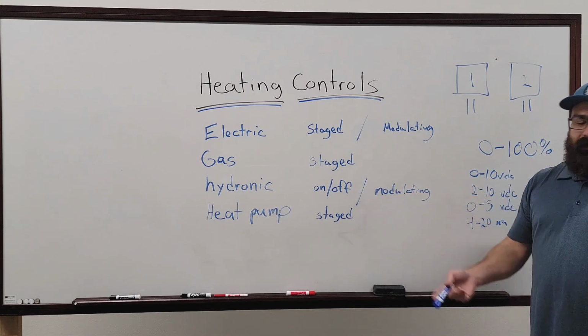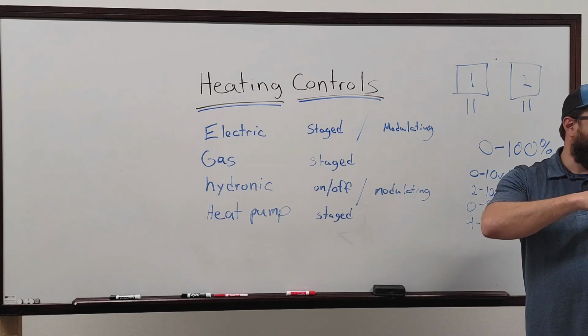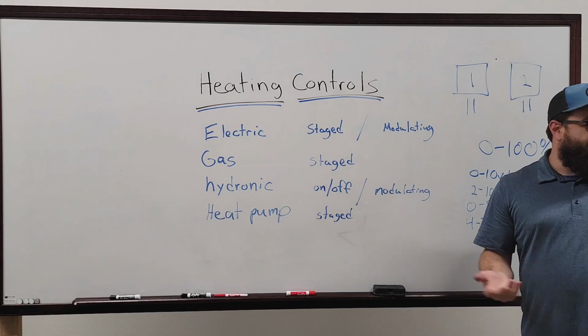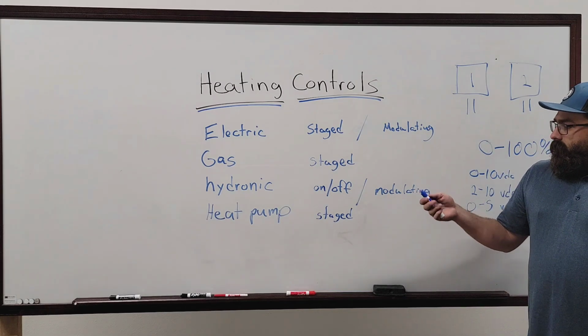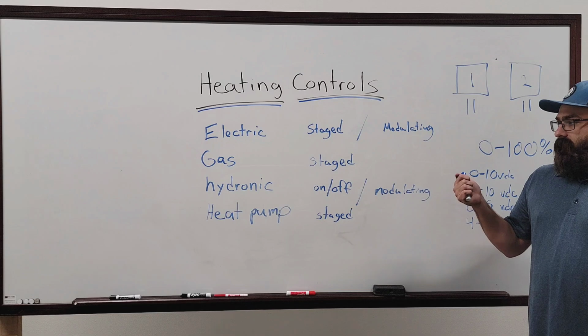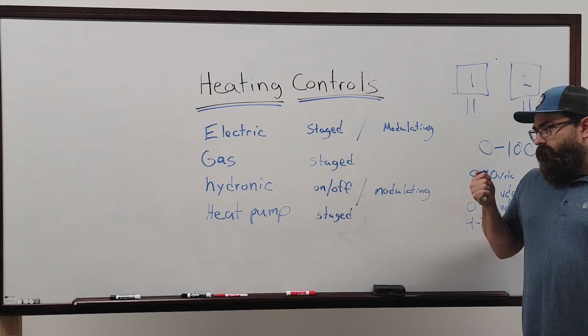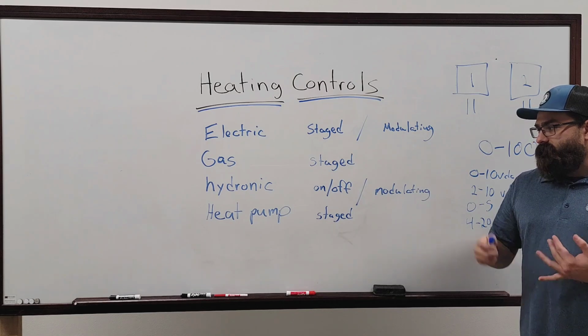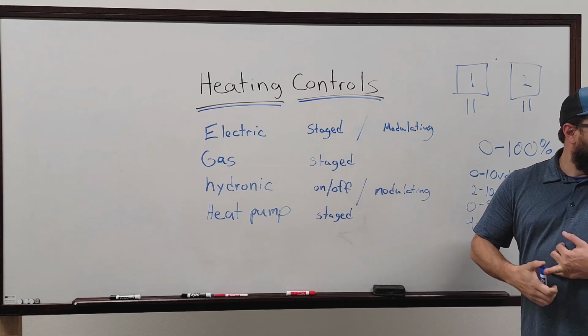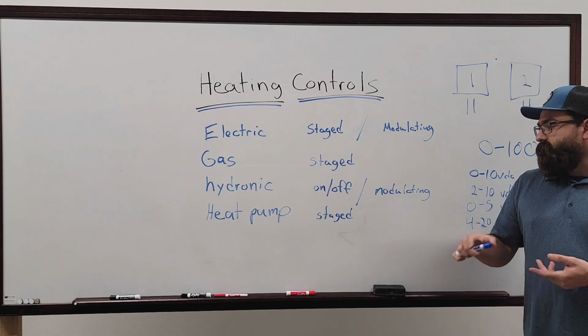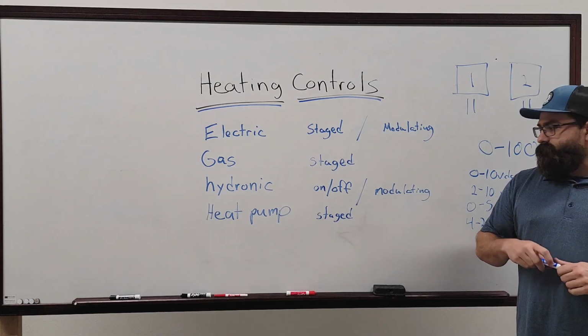Water would be a 0 to 100% on a valve. You open or close the valve. The more you open the valve, the more water you get, the higher the temperature. The deal with water is not all valves are modulating. Some of them are simple on-off, where it's either open or closed. You either got no flow or all the flow. Some of them are,